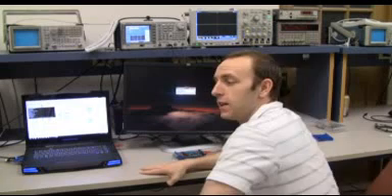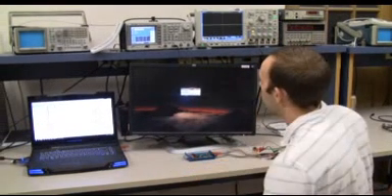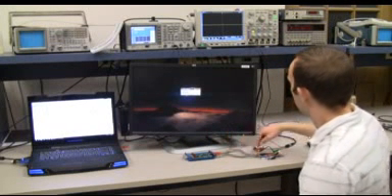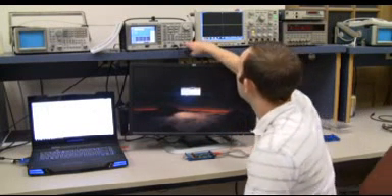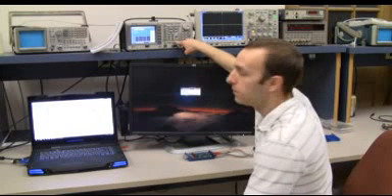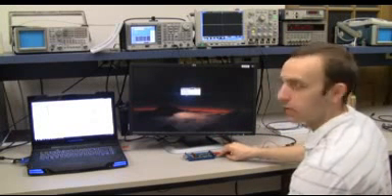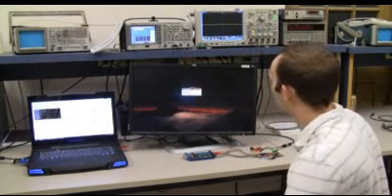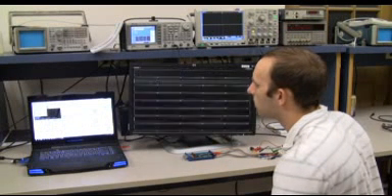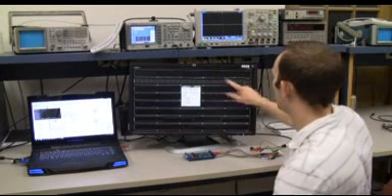Hi! Today we'll be showing you the functionality of the Logic Analyzer. Right here we have the Logic Analyzer probe. That's hooked up to the signal generator, which was producing a 50 kilohertz square wave. And the other set of probes is for the control signals. You start by launching the Logic Analyzer. We'll be collecting samples on channel 1, which is displayed here.